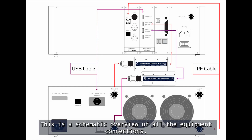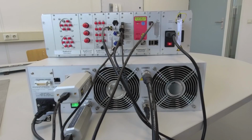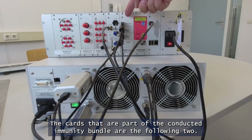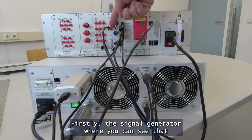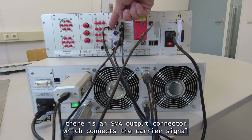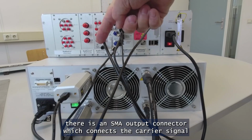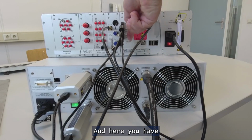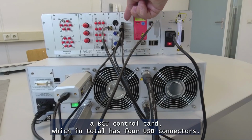This is a schematic overview of all the equipment connections. Here you can see the backside of the Radicenter unit, where we have multiple cards installed. The cards that are part of the Conducted Immunity Bundle are the following two. Firstly, the signal generator, where you can see that there is an SMA output connector, which connects the carrier signal to the input of the amplifier. And here you have a BCI control card, which in total has 4 USB connectors.